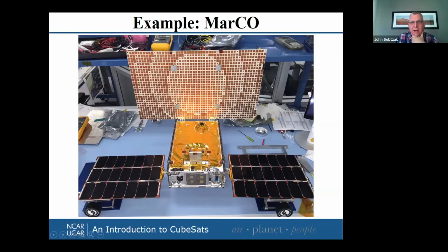On this little black dot right here, if you can see my mouse, is a camera. And the square patch over here, the aluminum, is the feed element for the reflector array. So it would actually send a radio beam from here. It bounces off the reflector array, hence the term reflect, and it refocuses the beam for a higher gain. So this lets you get a higher gain antenna in a smaller package.